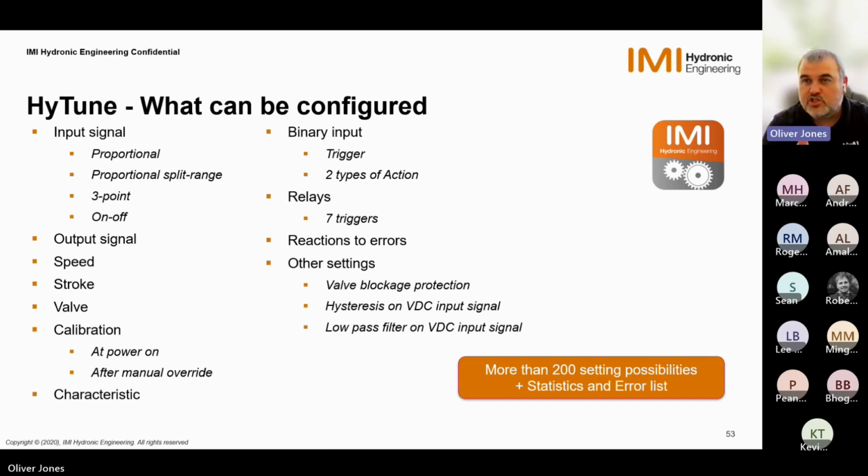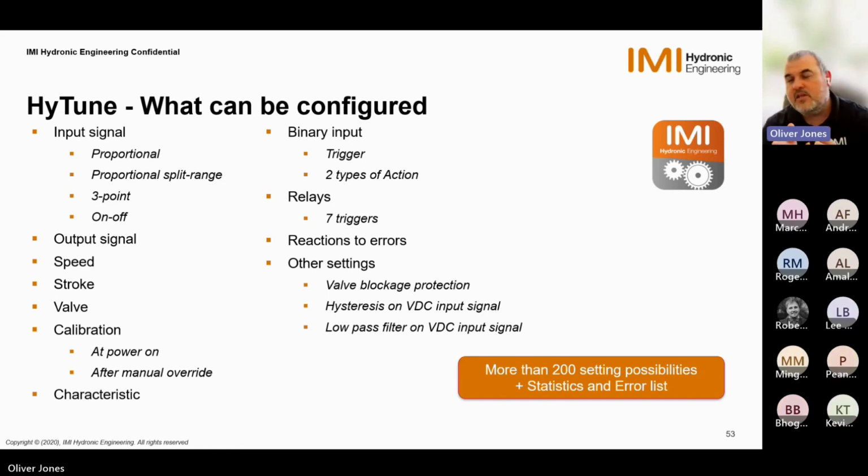Say it's a fan coil and it's 2 valves. We can control the heating valve with that 0 to 4.5, and with the cooling, we can control that from the same BMS point between 5.5 and 10 volts. You can set it however you like within the app itself as how it will work, but we can split those voltages within each actuator to say you will operate between X and Y, and that's exactly what they'll do.